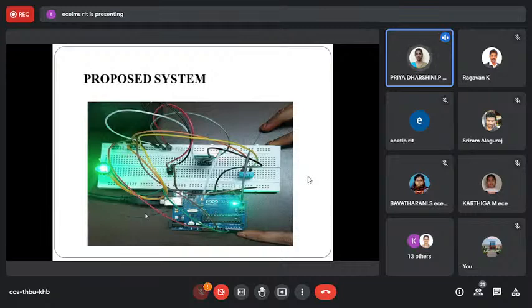LM35 is a temperature sensor for measuring the temperature of the external environment. LM35 has 3 pins, namely VCC, data pin, and ground. In this proposed system, the LM35 has been connected to the D2 digital pin of the Arduino UNO, and the heart rate sensor's data pin is connected to the analog pin A0 of the Arduino UNO. It is for measuring the heartbeat rate of a human, and the HC05 Bluetooth module is for connectivity, as we measure the temperature and display it on the mobile app by use of Bluetooth technology.